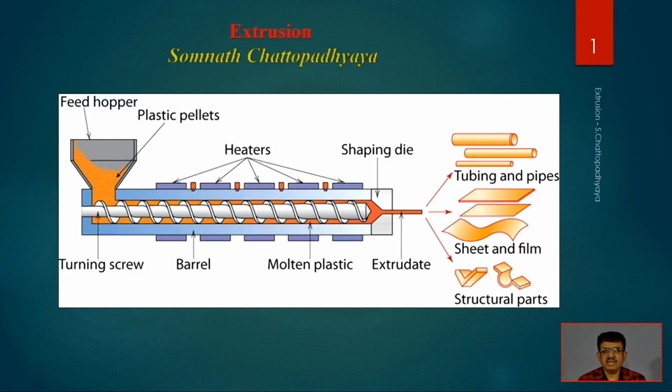The only limitation is that it has to be symmetric longitudinally. So variable shapes cannot be done in terms of the longitudinal one, and if it is symmetric cross section wise, then definitely we can do it in an easy way, and that is why it is popular. It was invented around 1800 at the time of the industrial revolution in the UK, and then some modifications like the use of a dummy block were innovated by German engineers in about 1890.